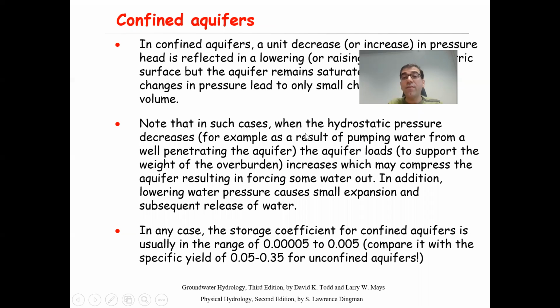In other words, and that is valid for the case of a confined aquifer, when the hydrostatic pressure decreases, for example as a result of pumping water from a well penetrating the aquifer, the aquifer loads to support the weight of the overburden increase, right? Because the water in the aquifer was supporting the weight of the overburden.